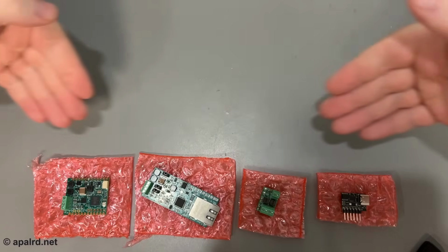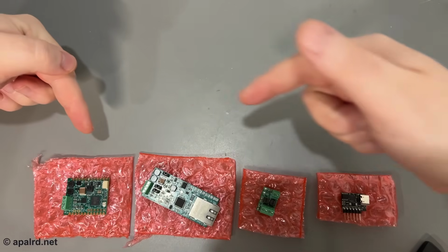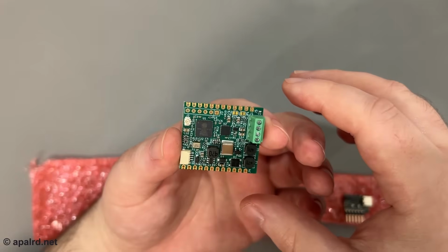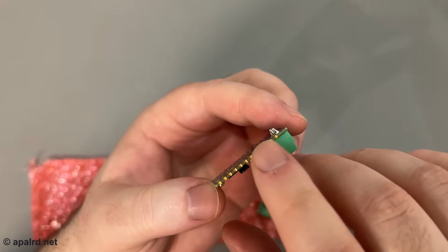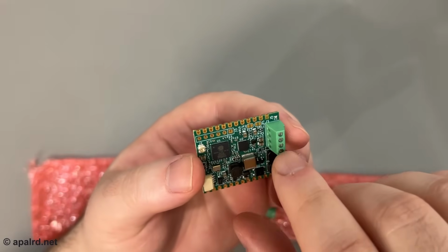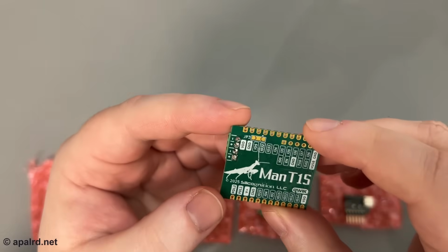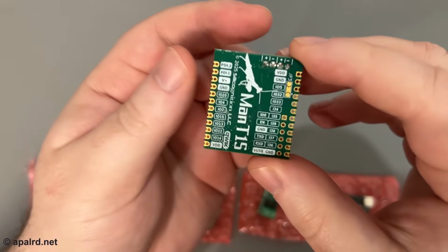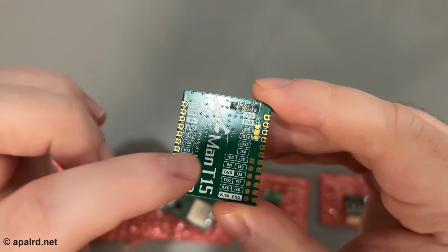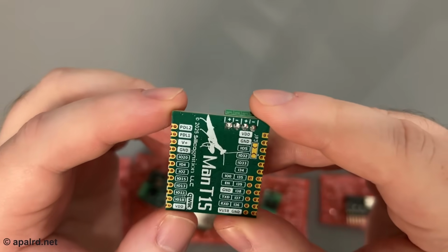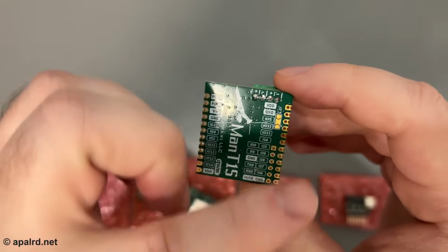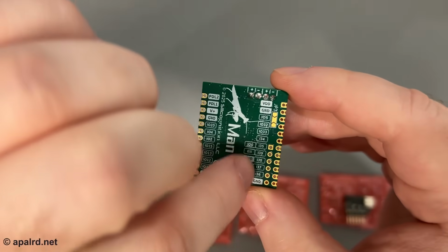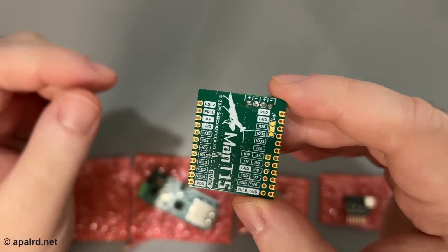So here's all the stuff he sent me, the Mantis itself, and some accessories. Taking a look at the Mantis itself first, it's a castellated board, so you can solder it directly onto a board below it, or solder through headers. Flipping it over, it says Mantis, obviously. He's helpfully silkscreened what all the IOs are, so these are all the ESP32 IO numbers, different voltages available, etc. I used literally every single one of these pins, except the ones in the programming header for my example.